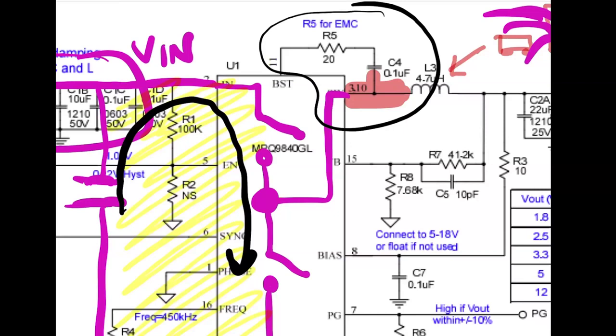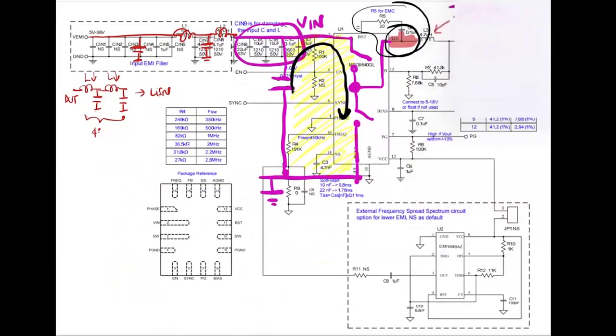So usually all the components connected to the switching node are not recommended to go through the layers, because going through the layers can corrupt other traces or other areas that are going close to the vias. So yes, put the components in the same place, in the same layer of the IC. Okay, and then why did you say the inductors were placed at the bottom? And this was kind of in the same place in the presentation.